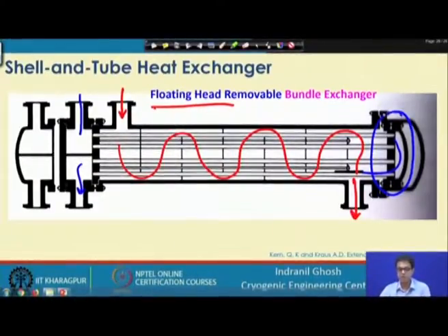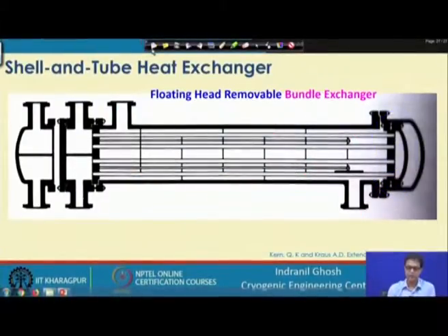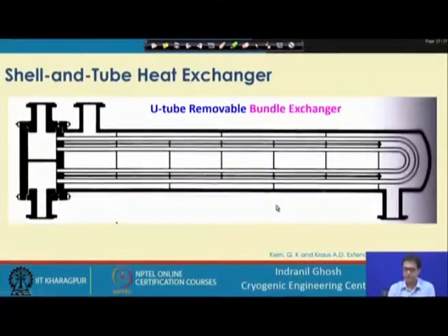If such situations occur, then the tubes will be able to expand as in contrast to the shell side. So, this particular type of exchanger design allows expansion of the tubes in contrast to the shell. They are not rigidly fixed with the shell side, and this is how it looks like.